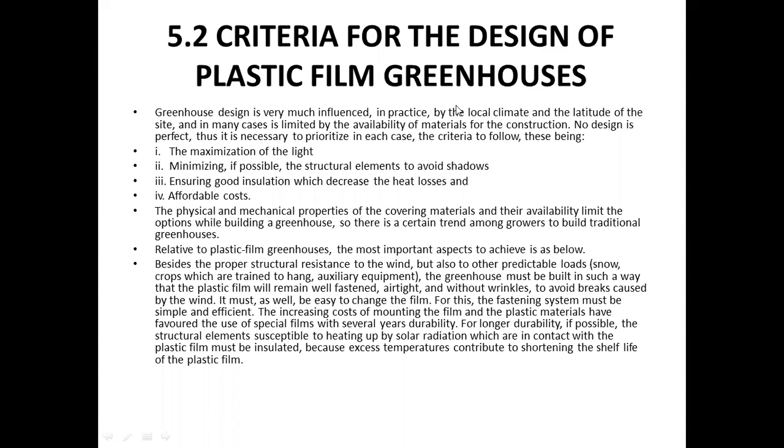Okay, also it should be kept in such a way that it is easy for maintenance and changing the films. Also, the increasing cost of these materials can give rise to the use of special films with more durability. For the longer use of plastic films or these roof covers, the films should be insulated from solar radiation, as solar radiation or high temperatures cause the plastic film to get a shorter life or get damaged.